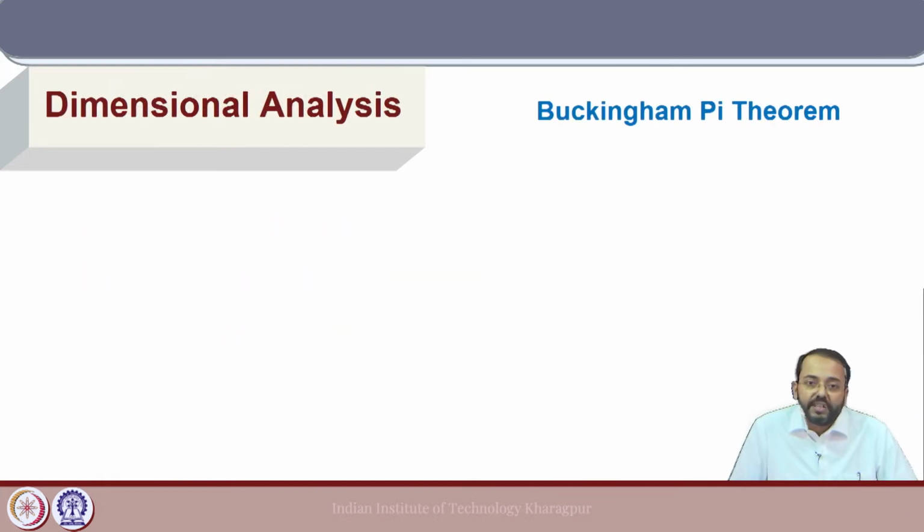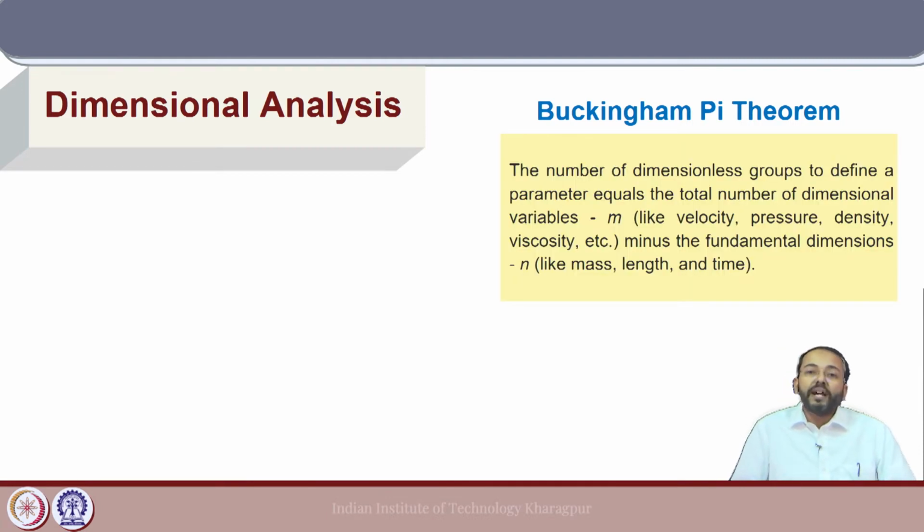For marine propellers, it is of importance to relate the model scale characteristics to the full scale with the use of certain dimensionless parameters, where we use the laws of similarity to do a dimensional analysis. So, we will use Buckingham pi theorem here, which is a popular theorem used in engineering as well as mechanics problems to relate a parameter with a number of dimensionless groups.